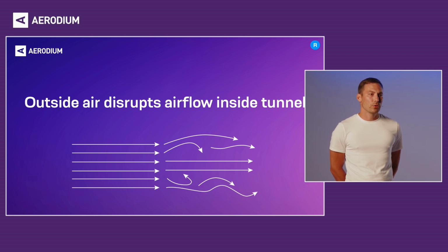But then you're introducing hatches, which are actually stepping inside the airflow and disrupting it. So at the end, this decreases the quality of your airflow, and it actually increases the power consumption for the machine because of the increased resistance.